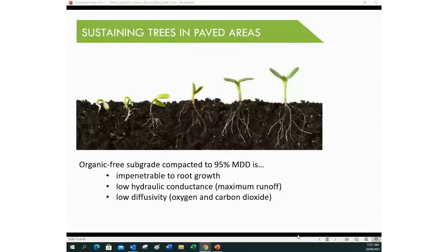Tree roots grow by cell division. The start of our lives, we were a single cell, we divided into two. That's the energy of tree root growth. Single cell dividing into two, right at the tip of these very fine roots. If there's no pore space in the soil, the cell can't divide. If there are two equal pore spaces, one has water, one doesn't, the surface tension of the water draws the dividing cell into it. So roots will track up a water gradient. It's not a seek and destroy. There's no such thing as an aggressive tree root. It's a physical response to surface tension of the water. So there's a clue we can work with. If we can get the water where we want the roots to grow, maybe we can solve some problems.